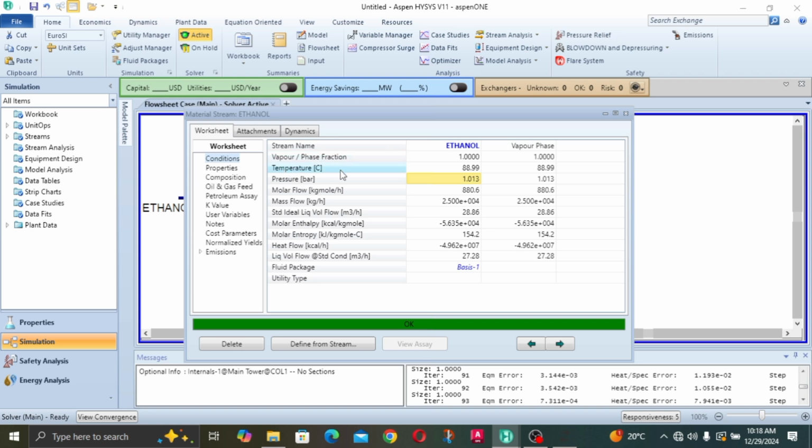So then you need to take note of something very, very important. Our vapor rate that was specified, 25,000 kilogram per hour as a vapor rate. That's basically the flow rate we expect for the vapor, and that's what we have reflecting in our vapor. So it matches, and then we head to the composition, the moment of truth, to know how much we are able to separate.